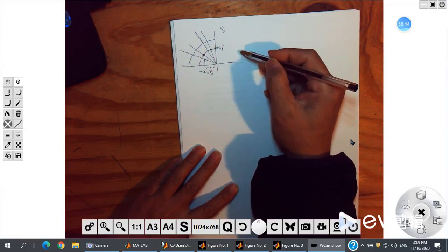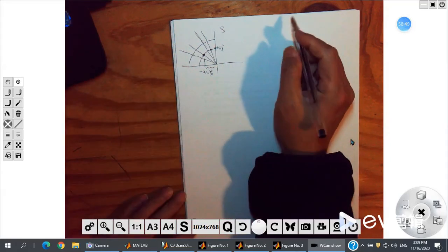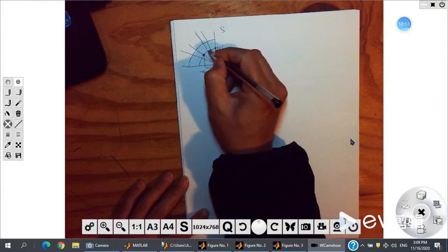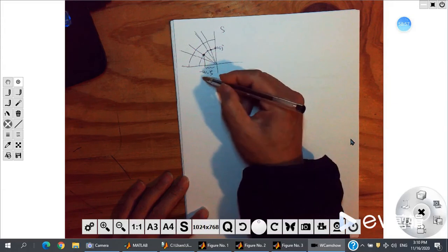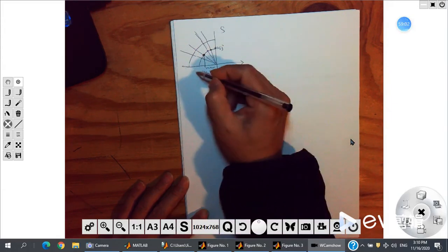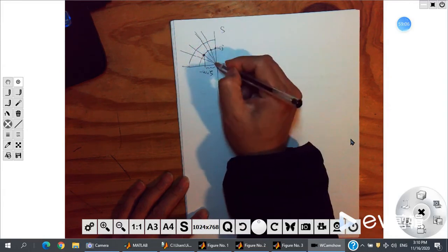We don't want that. You design something to find the parameters, not to make the system unstable. We are interested in poles at this kind of point. Below the real axis, they are symmetrical with the upper side, so we only need this part.